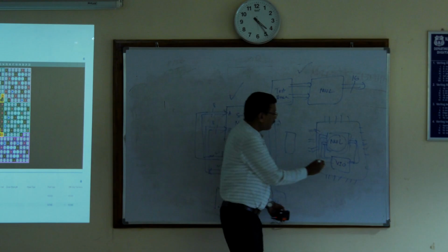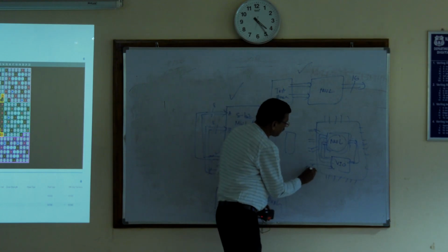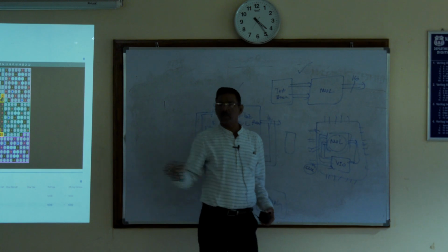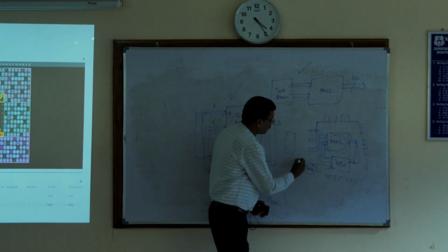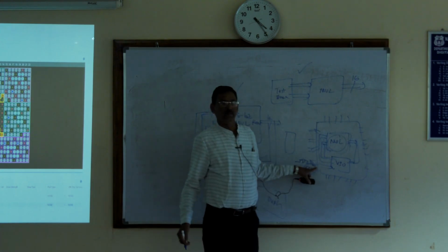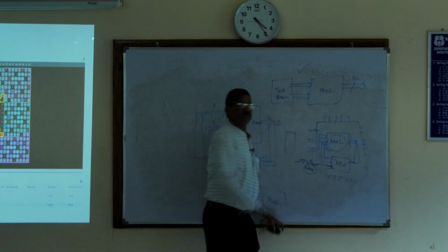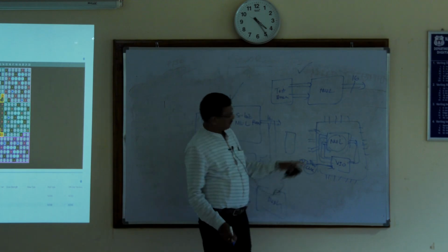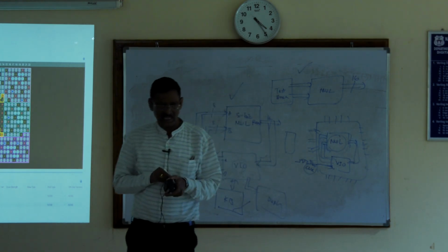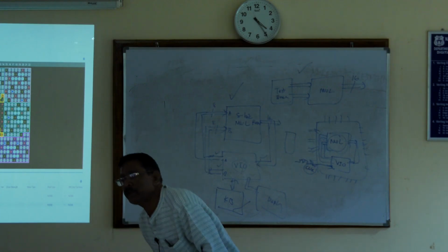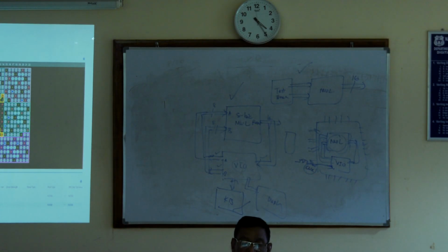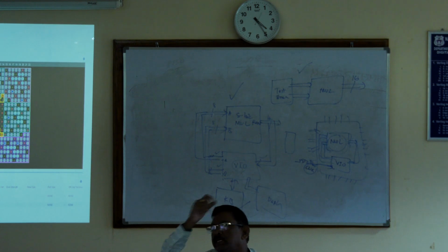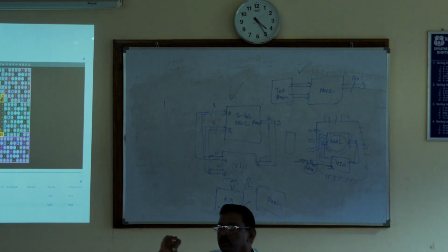So only the clock connection has to be made, one external clock pin, because an external clock source is there and the clock signal is going from one pin. That clock only we have to connect to this. That's all, nothing else. Only one pin assignment is required. Okay, understood this? That clock pin is a default, a fixed pin always. So that is Y9. One pin, Y9, is assigned to clock. Clock is connected on the board to one particular fixed pin only.